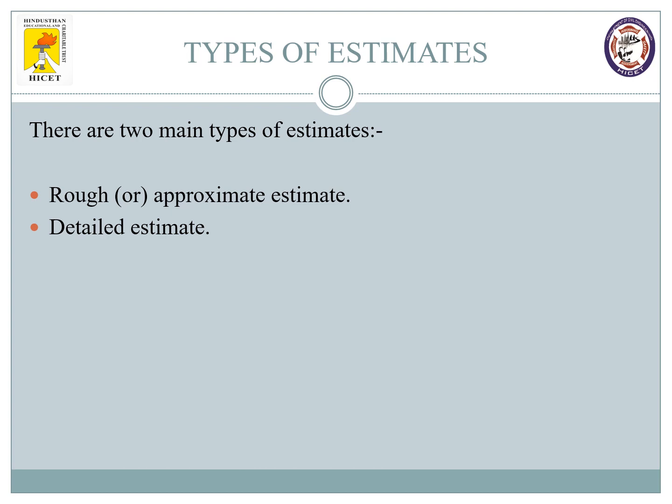Like I can tell this project might be coming around 60 lakhs. That is my approximate estimate. By experience or foresight or other thumb rules or basic calculations, I will be arriving at those values. And on the contrary, if I'm going to give my clients the exact amount of my project, I have to do my detailed estimate, where I'll be calculating each material, labor, and other small things combined, and I will be able to give the probable cost.